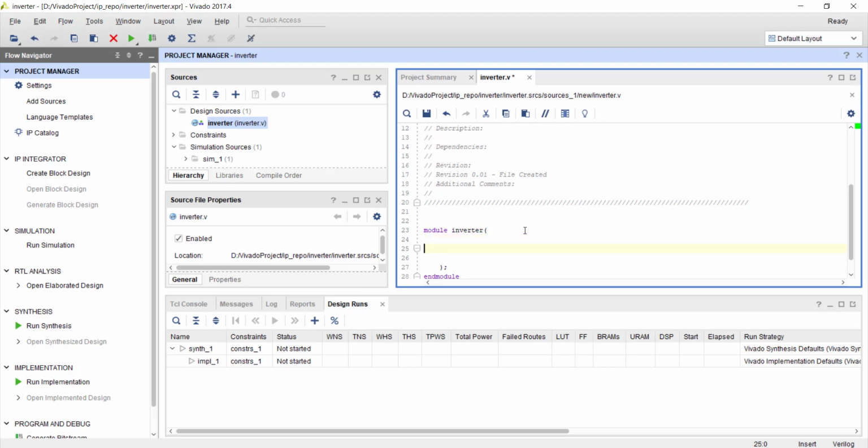Now, as I mentioned before, what happens is the inverter gets some data and he takes byte by byte from that and subtracts it from 255 and sends it out. So he needs an interface which accepts data. He needs an interface which sends out data. Both follow AXI4-Stream interface. Now the interface which is accepting the data, that is a slave interface.